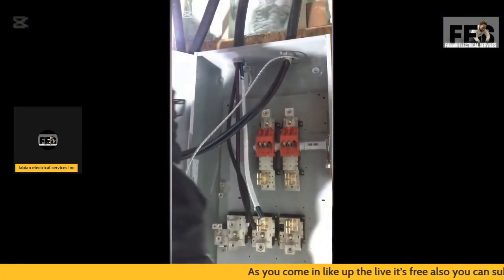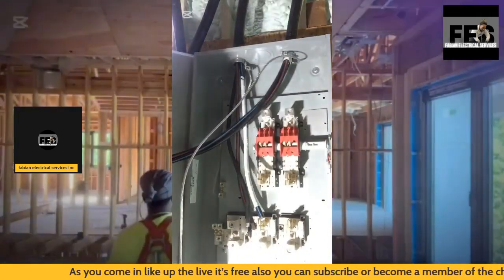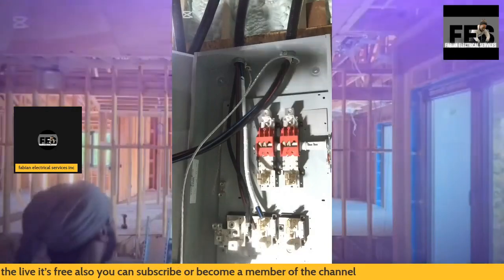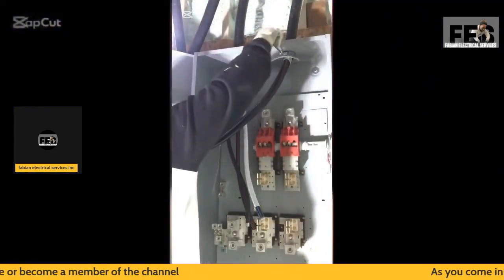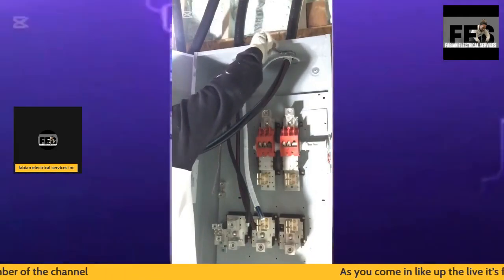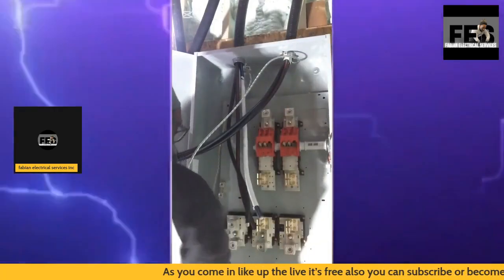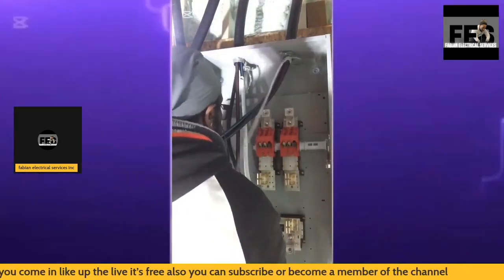So as you can see, the reason why I like to keep the white paper on is it simply helps with the cable. As you can see, the cable is locked in place. Once you disassemble that, it gives you a lot more problems to get the cable inside of the connector. So again, that's why I always make sure I land my cables inside of the disconnect, inside of the connectors, and I make sure that I remove that.